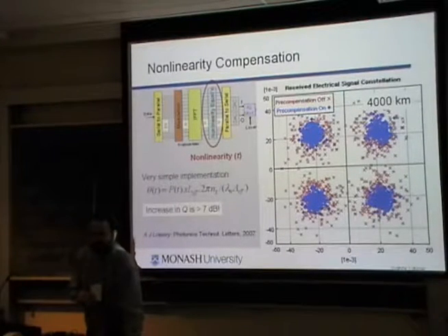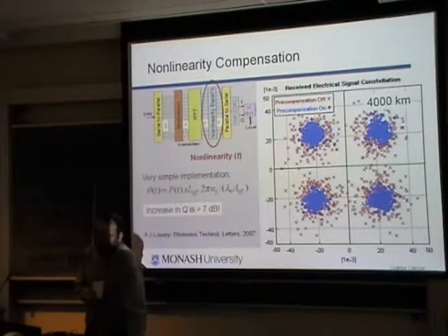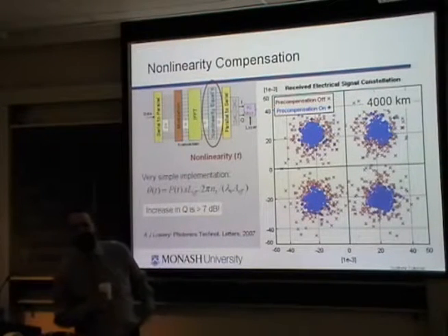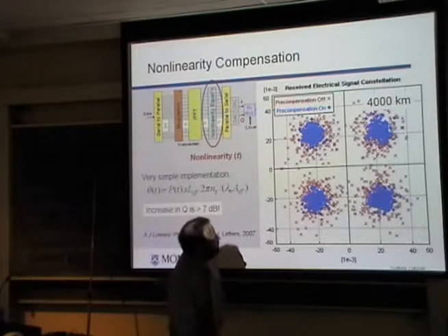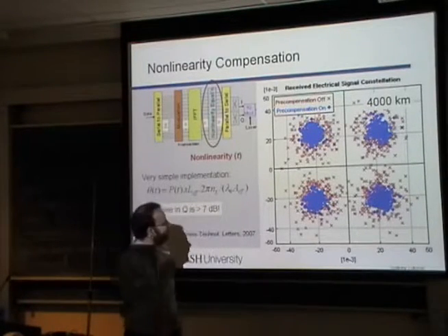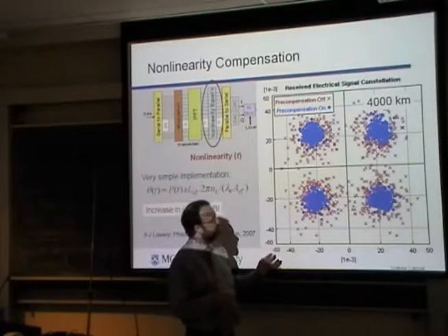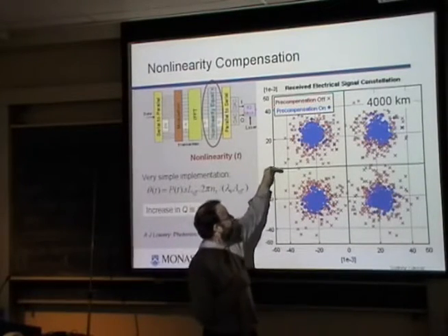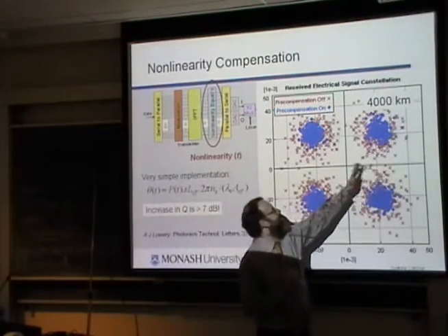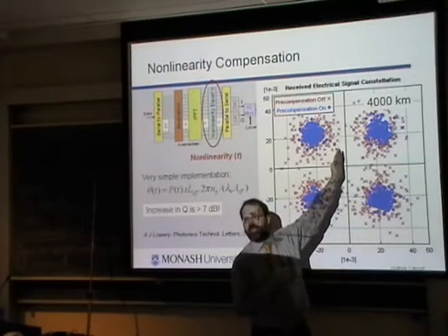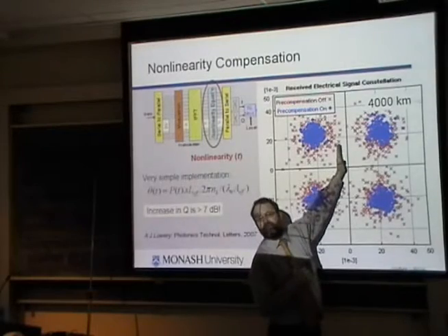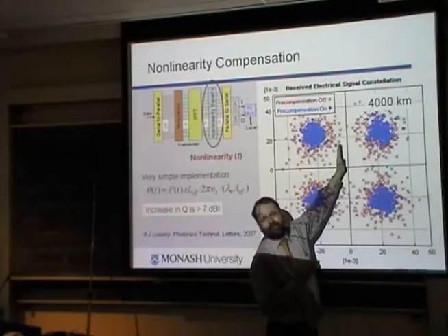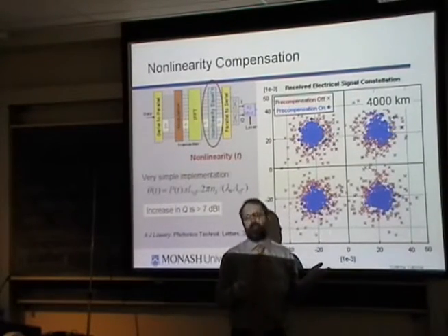Any questions? Is that surprising or obvious? What are the axes of this diagram which you're displaying? Oh, okay. So this is a constellation diagram, and it's basically saying there's a real axis, it's an Argand diagram, and an imaginary axis. Communications engineers call this in phase with the carrier, or quadrature, 90 degrees out of phase with the carrier. And that's what QAM modulation is.